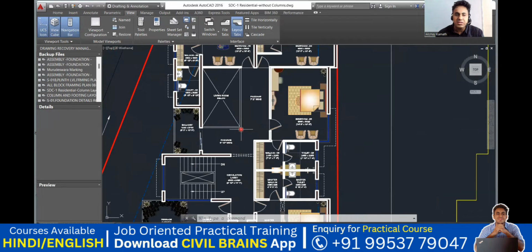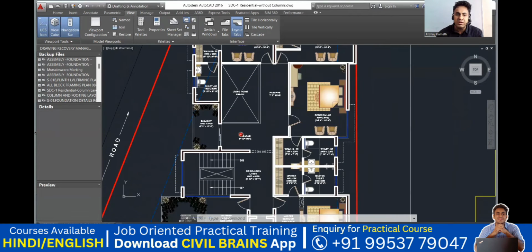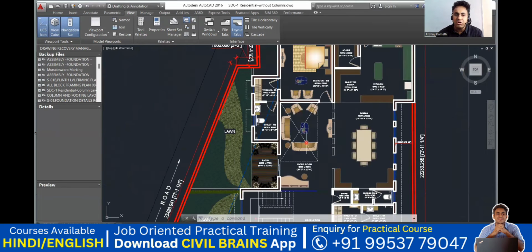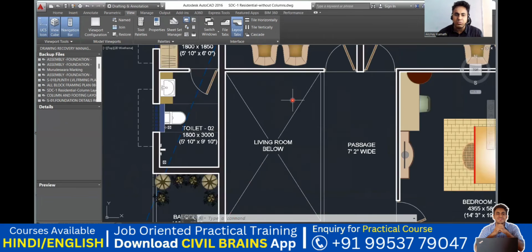Okay. So passage, even this is also passage. So this means it's an opening. Whenever they put a cross mark, that means you don't have a slab here. From the top, from the first floor, you can see what is happening in the ground floor, this much area. So this entire living hall, whatever living hall is here, that can be seen from the first floor. So you can see the X mark here. That means there is no slab here. It's a cutout portion.